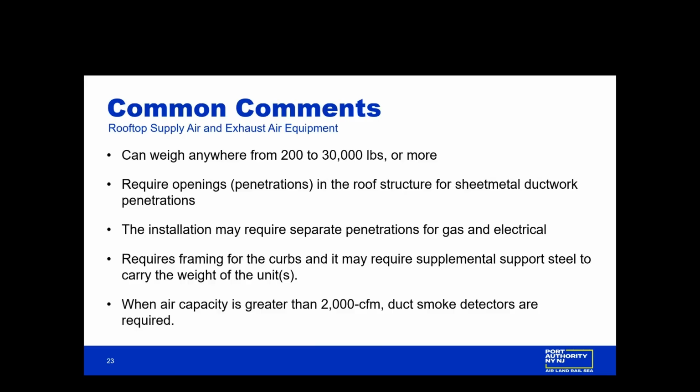And then the other big thing is whenever there's air capacity of a unit that's greater than 2000 CFM, duct smoke detectors are required. Now there are different caveats and stuff like that, so please check your jurisdiction and check the code for the use of duct smoke detectors. Next slide, please.